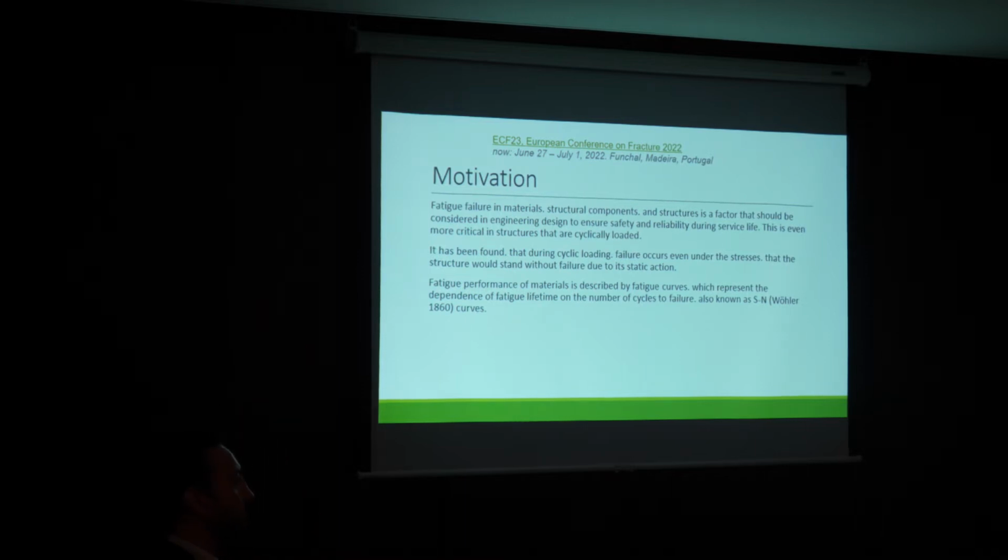This means that a car is going through, or some high-speed train or other fatigue load, and that could initiate some cracks, and the cracks lead to failure of the construction. As we know, the dependency of the load can be captured by the SN curve, also known as the Wöhler curve.